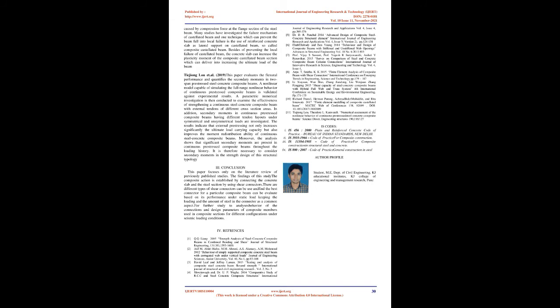The effects of the shear span ratio, the angle A between lateral truss plane and vertical plane in cross section, the angle B between inclined truss and vertical plane and longitudinal plane were reported. A shear strength equation that considers the shear contribution of the concrete flange and the shear strength provided by the web of the steel beam and inclined truss system is proposed.